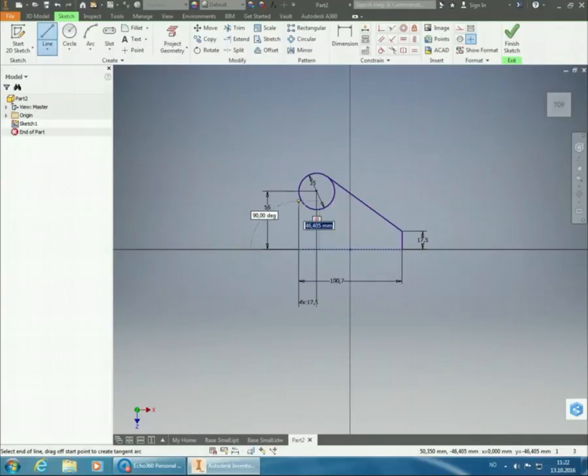And here we are going to hit the exact 90-degree angle of the circle. So there will be one of those green dots there which we can connect to. We don't need to do the tangent stuff on this one. So we just go upwards until we get it. Actually, Inventor is even telling me here that it's going to be a tangent when I connect it there. So then we get a full connection there.